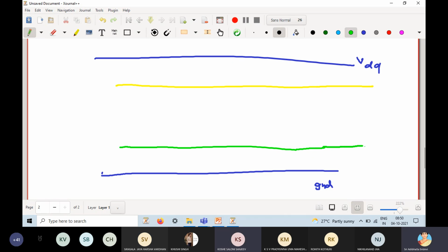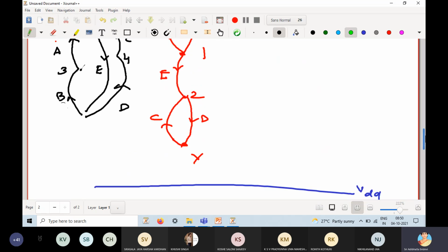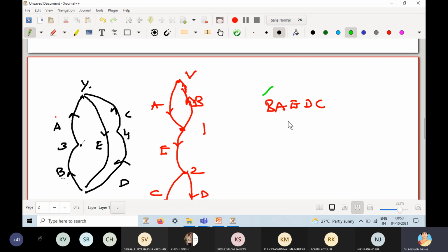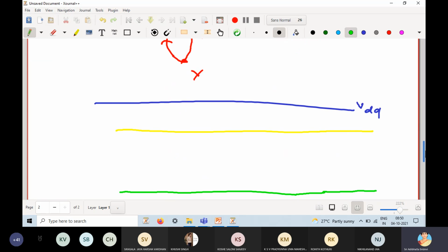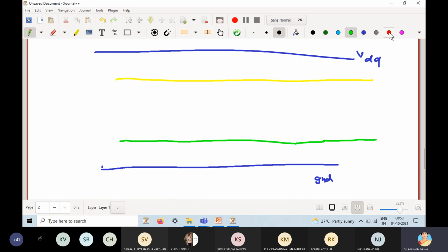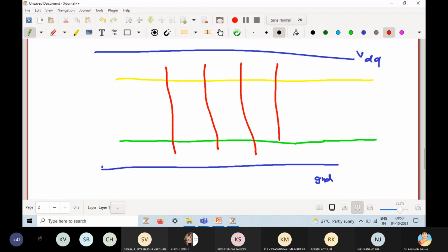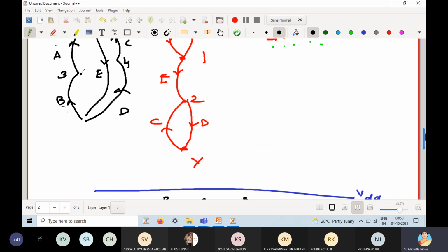Five inputs. Actually, why we need Euler path is this order is very, very important. B, A, E, D, C is our Euler path. So you take 5 inputs: 1, 2, 3, 4, 5, and give names B, A, E, D, C. This is the most important thing.